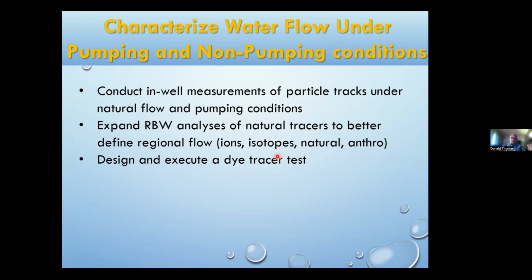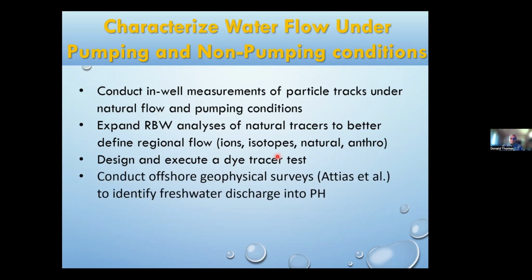And with all of that data then as guidance, we will plan to design and execute a dye tracer study where we would inject a dye tracer into a carefully selected well and then monitor wells that, again, our preponderance of data suggest is the direction of water flow.